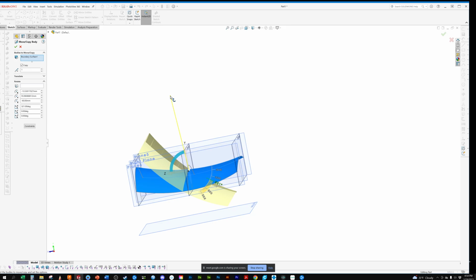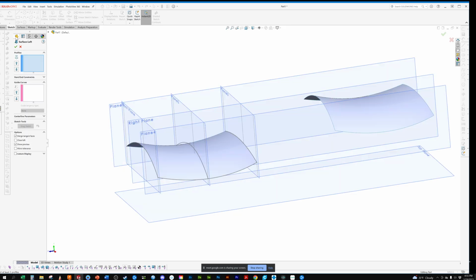What I want to do is if I go loft, I can loft from this profile. And we'll get into this later. When you're building from one surface to the next surface, you don't want to use the curves. Anytime that you can use a surface edge, it is considerably better because it gives you more control, because there's more math geometry happening behind the surface, and we'll go into that too, versus using the curves. So I'm going to come in here and let me just hide that sketch there so I'm not accidentally grabbing that. Oops.